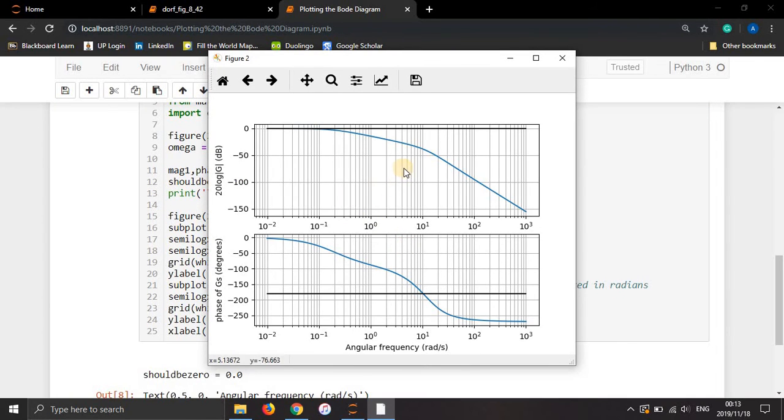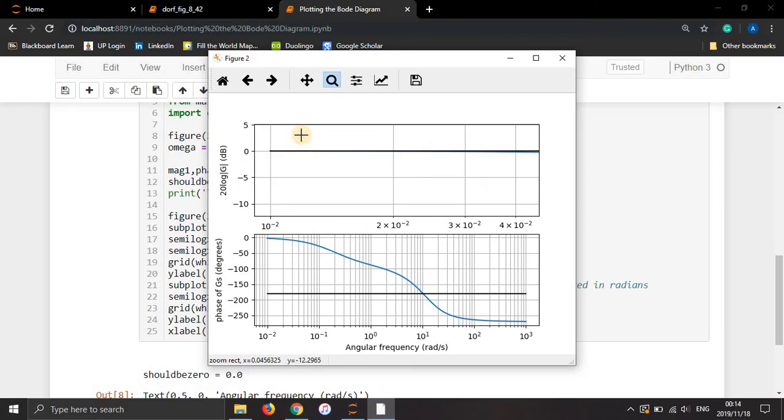So you can see straight away that the Bode diagram is different. And notice on the gain plot that at very low frequencies the DC gain is 0, or the magnitude plot goes to 0 at low frequencies. So this isn't always 0, this can be some other value, but for this transfer function it is 0. So to measure the bandwidth, we're going to find whatever this DC gain is minus 3 decibels and draw a line across the whole thing.